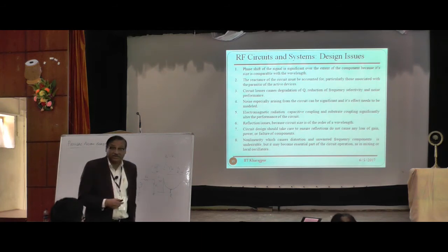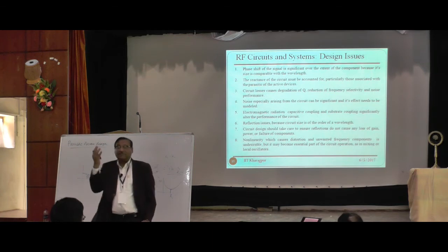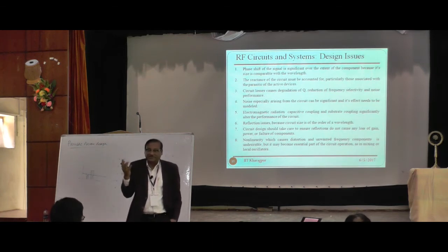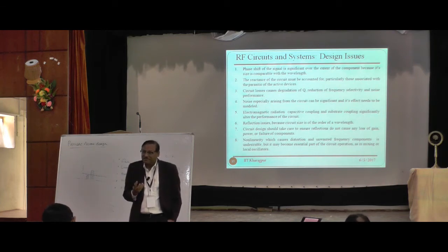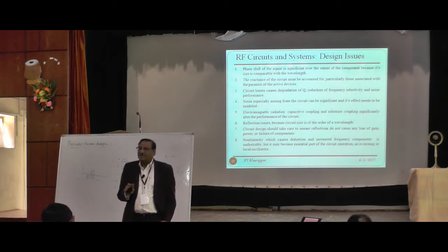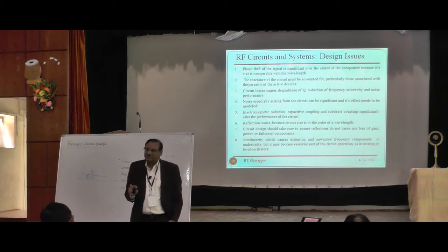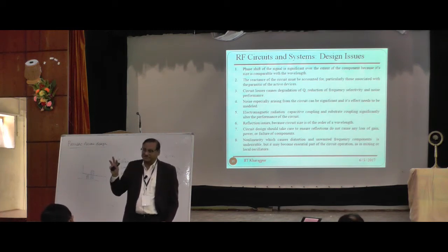But in some cases you require the nonlinearity. Multiplication of two signals, a mixer, is a nonlinear operation. Or an oscillator, this is nonlinear. So you sometimes need the nonlinearity of the circuits, but in a very constrained way, so that it never goes to an unstable state.